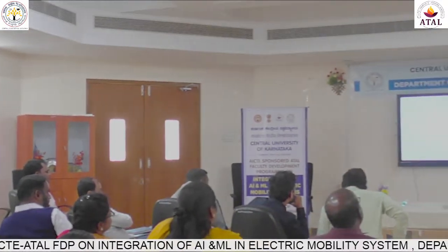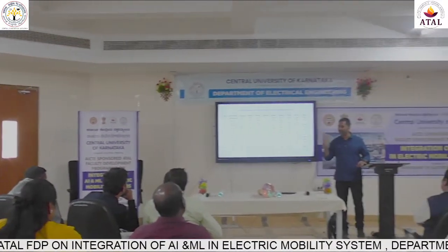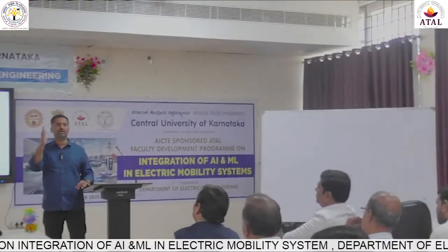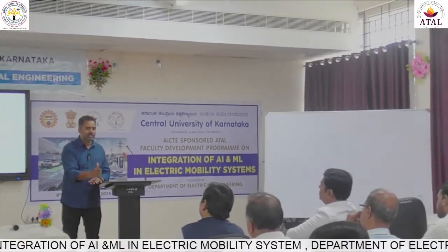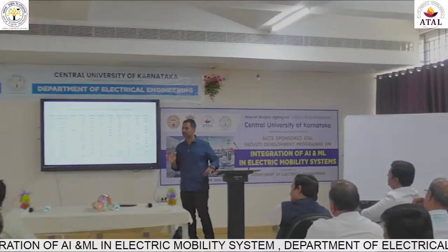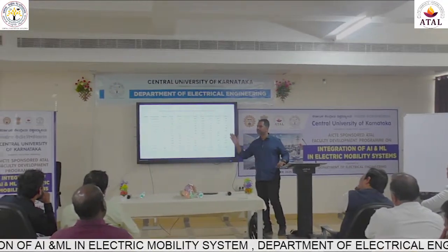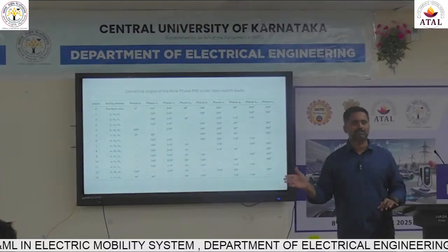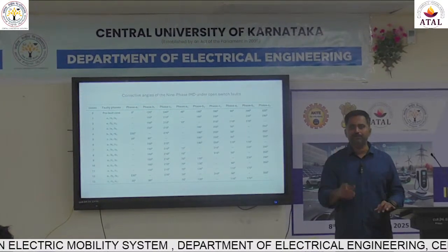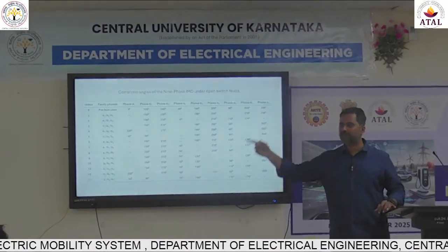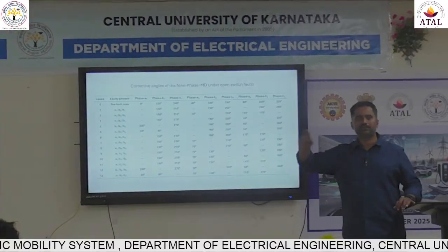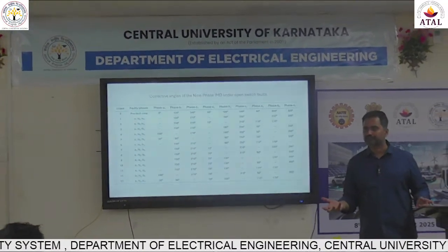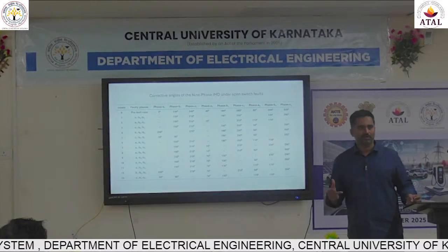Why were batteries required? Because at fault times, the signature of discharge currents will be different from the regular working condition models. The discharge signatures in the working condition will be different, and in fault conditions the discharge signatures will be different. And if you go with a very conventional, monotonous battery discharge SOC by thinking that the current signatures will not change, then your entire analysis will collapse. Okay, so it is very simple.